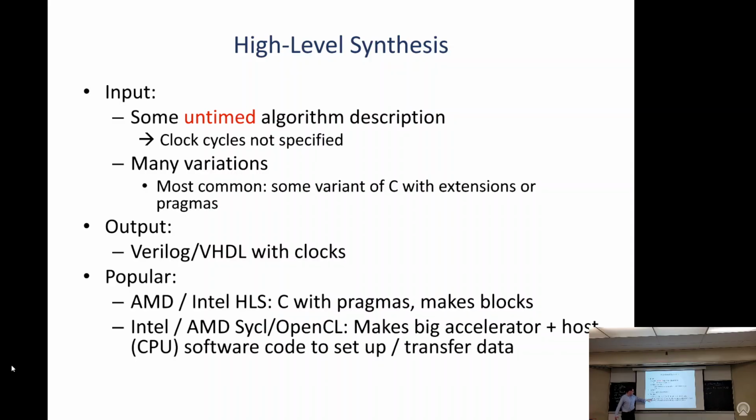There's another use of high-level synthesis, which is to build an entire system. Both Intel and AMD have tools based on OpenCL, which changed its name at some point to SYCL, so these are kind of the same thing. Those make the whole system, all the hardware, and they actually make the host code. They assume there's a CPU that is controlling the whole system. The nice thing about these specifications is it's all in one set of code, both the code that will turn into the hardware accelerator and the host code that will set it up. It has proven difficult to get really good performance out of this.